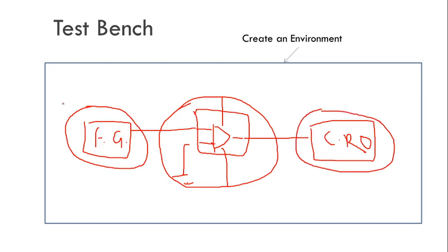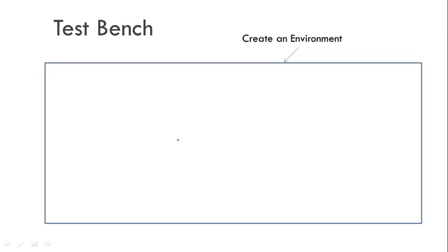So all the facilities are available in an environment, and that environment we can call a test bench. Here, with respect to your Verilog code, we create an environment. That means we create a module where we test our design, and our design is the decoder 2:4. For that we need the input and output to be present in that particular environment.